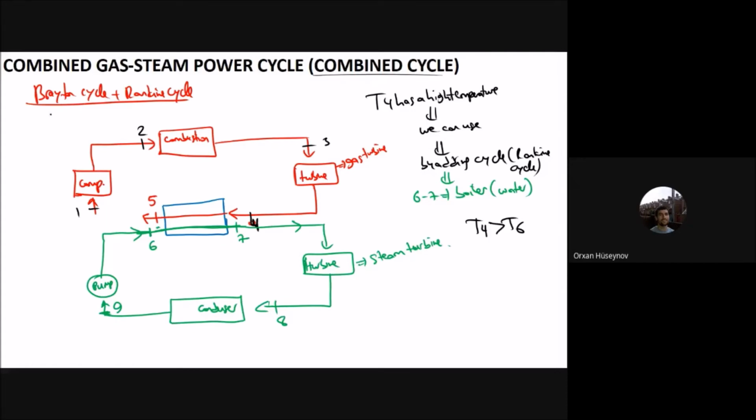Okay, this is how we get the Brayton cycle. And if you want to complete the cycle, you can add one more component here. This component again will be a heat exchanger, and you will have 5 here and 1 there. This one is to make the cycle closed. So to close the cycle, I add one more heat exchanger here. This one allows the temperature T5 to drop to T1, and the cycle is back to its initial values. Then it can start one more time in this way.